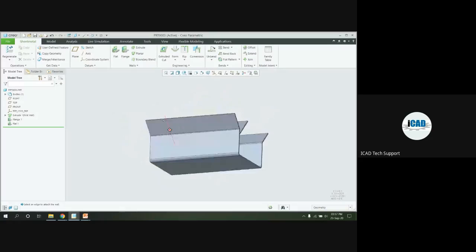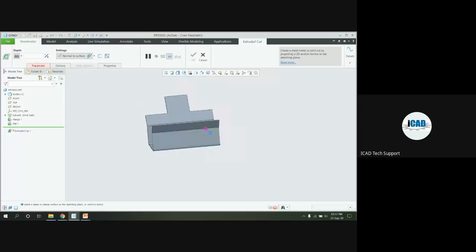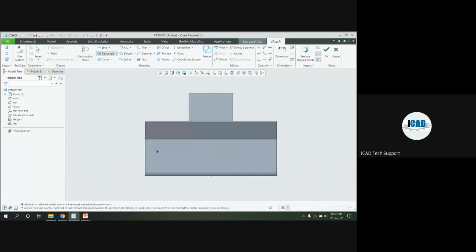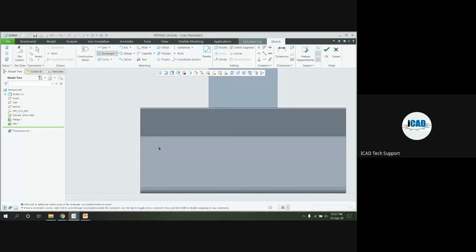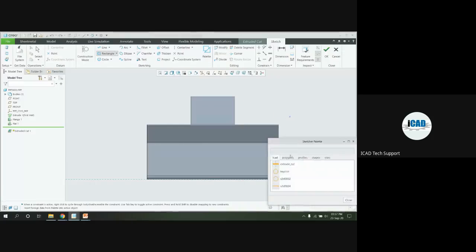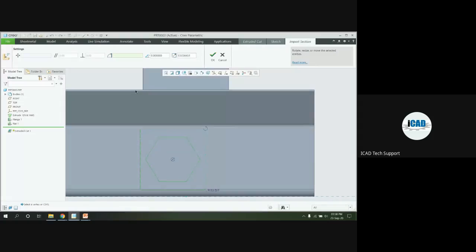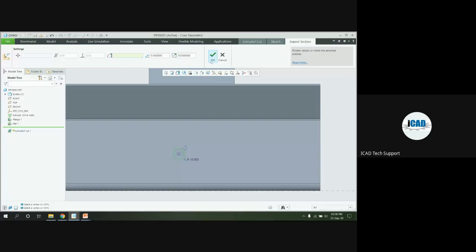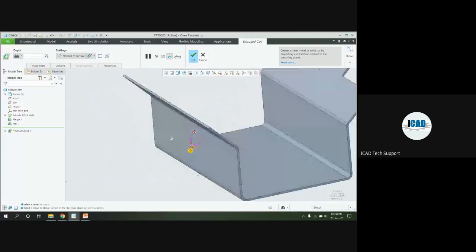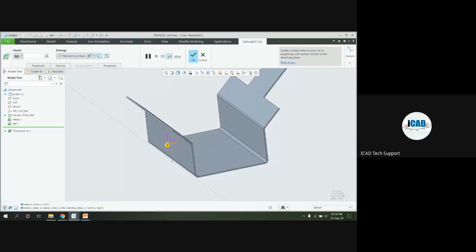If I want the extrude cutouts from the surface, here I can set it and, from the palette, I can use the hexagon honeycomb shape in small size. Click on OK and directly click on OK. Now you can see automatically the extrude gets cut out up to the next surface.